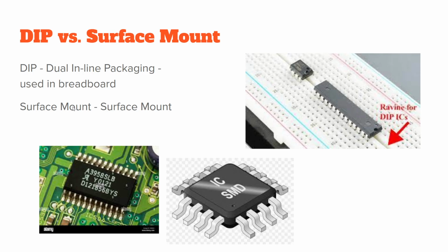The other one is called surface mount, and surface mount has to go through a process called soldering. Soldering, we did that also. Actually, we did that last Friday, where we got to play around with solder and try soldering something. So these are surface mounted onto what's called a PCB. They come in lots of shapes and sizes. I don't want to say they're more high performance, but they're used more in high performance equipment just because of their size.